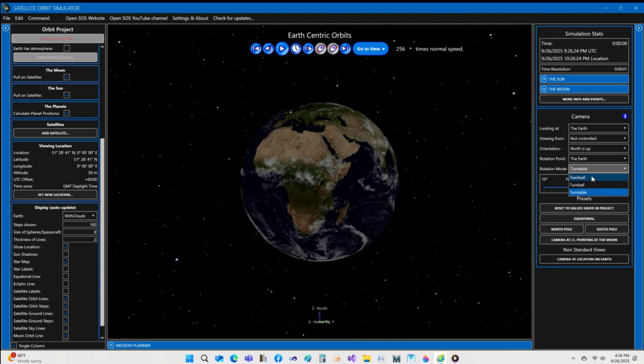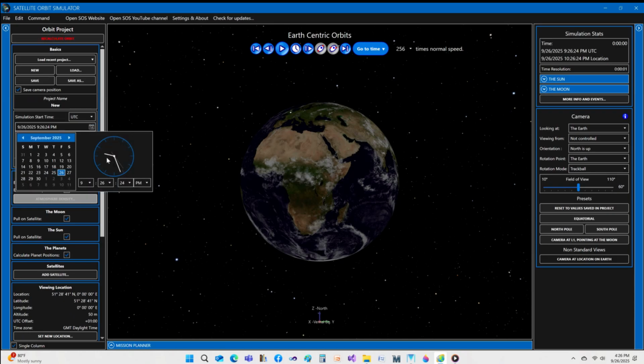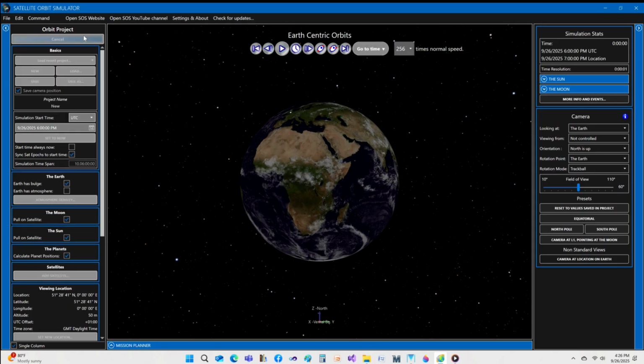local time. Just keep in mind that due to your location in the time zone, this may not be exactly between solar noon and midnight. It may be necessary to make fine adjustments to the start time. You may choose any start day that you want. Next, add 10 days to the simulation duration so we can clearly see the orbit drift over time. Press the Tab key and then recalculate the orbit.